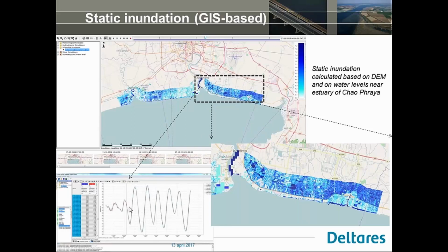We take the scalar time series of the water level forecast from D-Flow FM and integrate them into a grid, which is shown in the viewer. Then we use a PCRaster module to subtract the underlying DEM from this two-dimensional water level area.